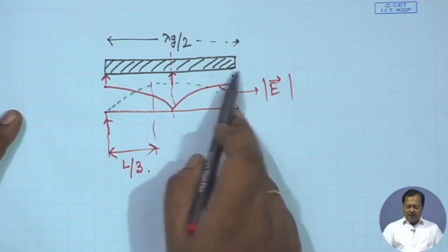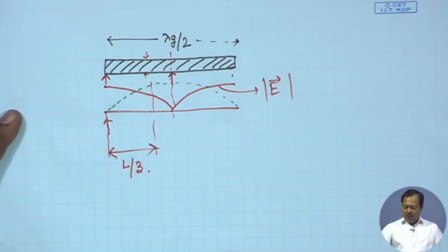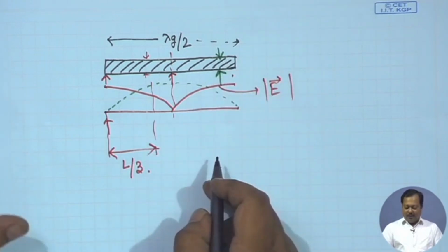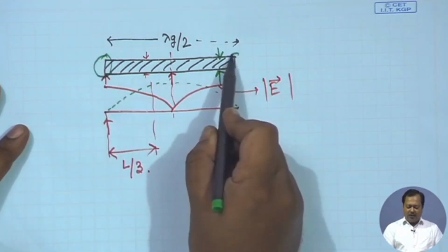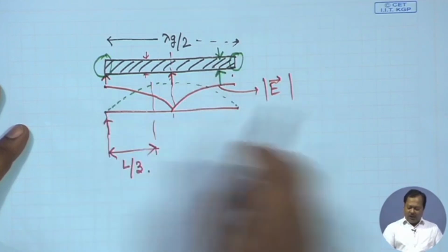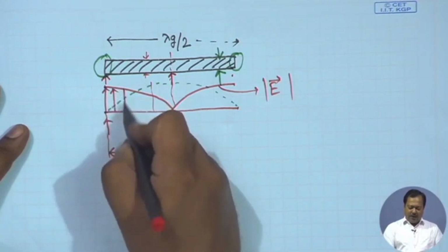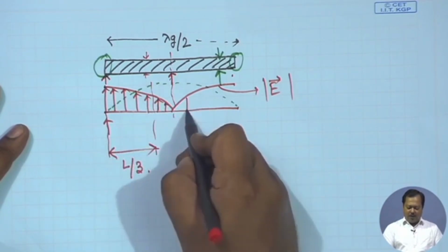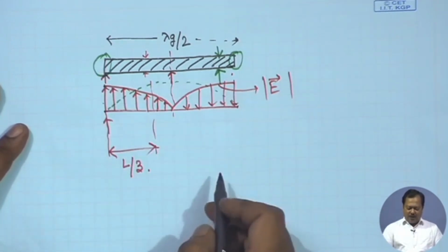This resonator, when its width is very small, will not radiate, but if we keep on increasing the width of the resonator, it starts radiating, and this radiation comes from the fringing field at these two sides. If I look at the fringing field plot, this is the direction of electric field. I did not show it in this diagram. Since it is radiating, if on the left hand side it is upward, here it will be downward, and at the end we have fringing field.